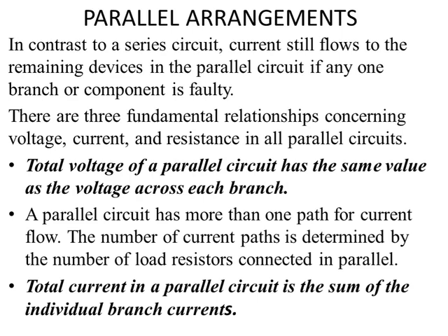To me, I can actually say the parallel arrangement is the best for buildings, for homes, because if you followed the series arrangement in any building, in homes, in our offices, in our places of work, and one of those components is faulty, then the whole building will go blank. There will not be supply. But as long as the parallel arrangement is followed, even if one part is faulty, it won't affect the other areas, because they will work irrespective of the one that is faulty.